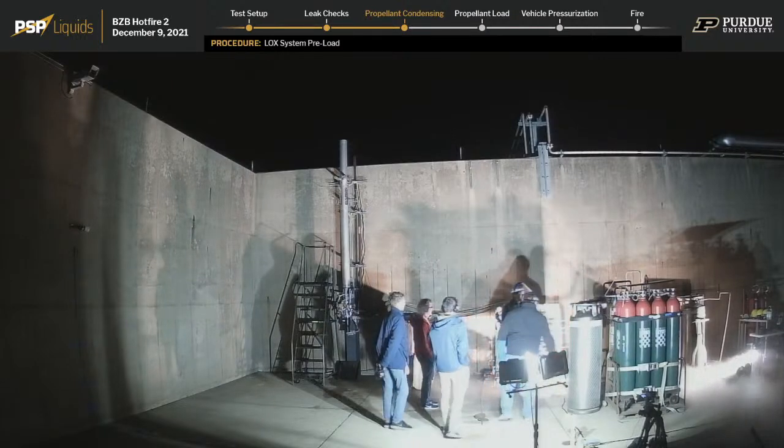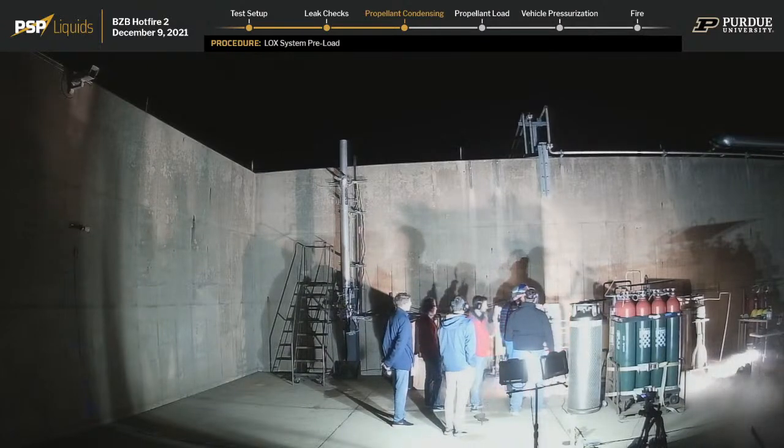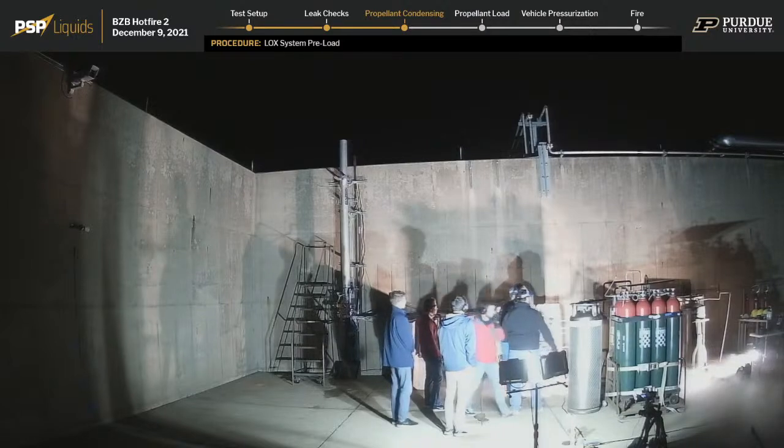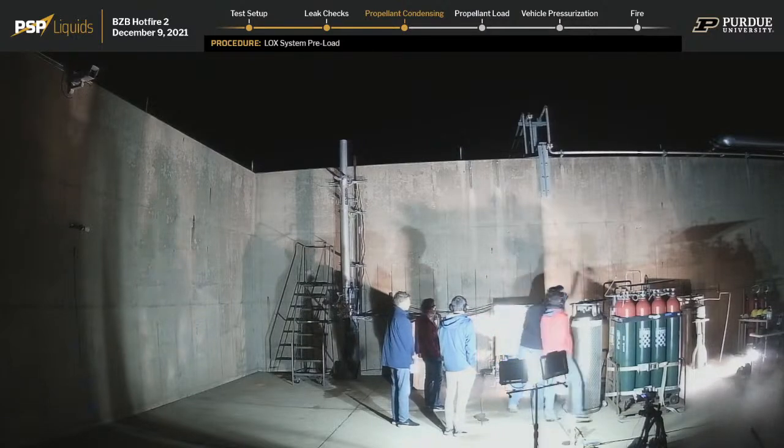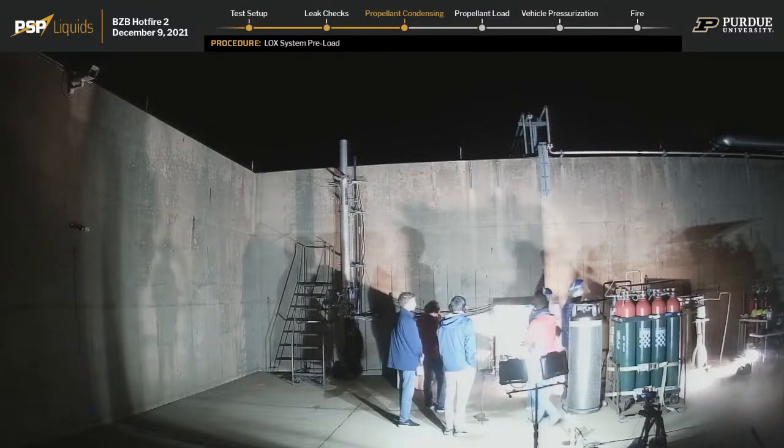What is that? What does it do, and what's the effect on the overall rocket? The dewar is at 80 psi. Over. Copy. So when we run the pressure build circuit, that allows us to build our pressure in the dewars, and that allows us to fill at either a lower or higher pressure on the actual rocket.